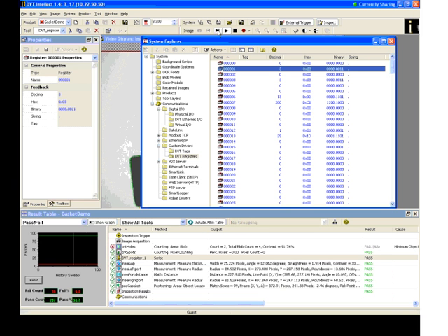So as we activate this, we'll see this turns to a 3. The reason why it turns to a 3 is because bit 0 is 1, which is high, and bit 1 is 2, which goes high. So that means 2 plus 1 is 3. So in that register, we are holding a 3.